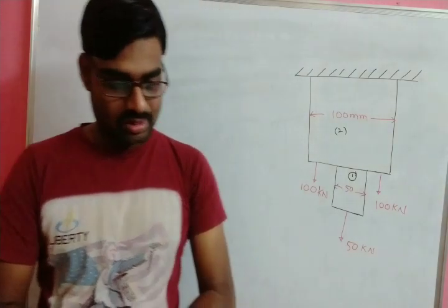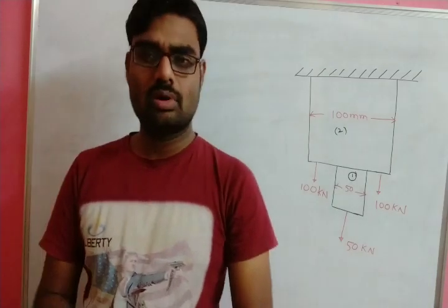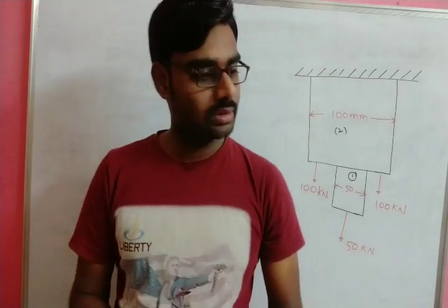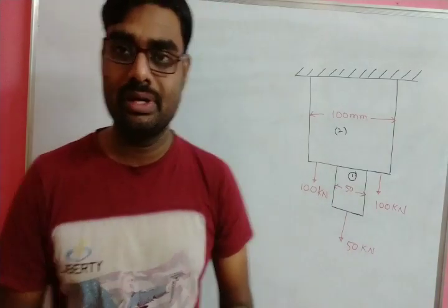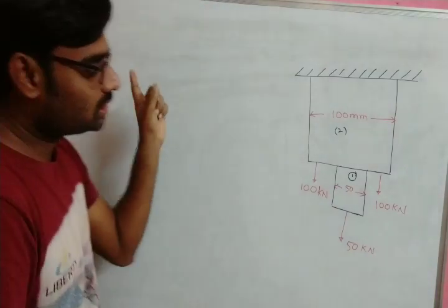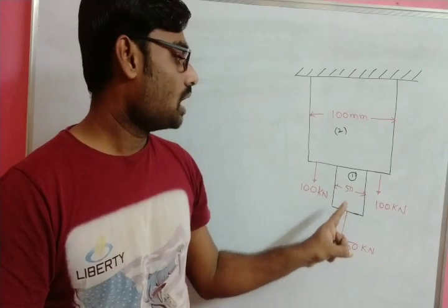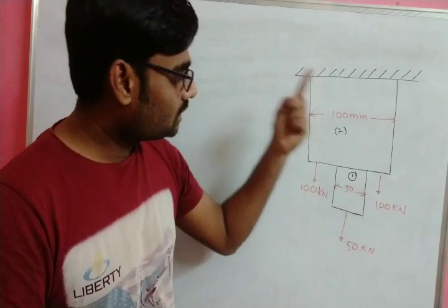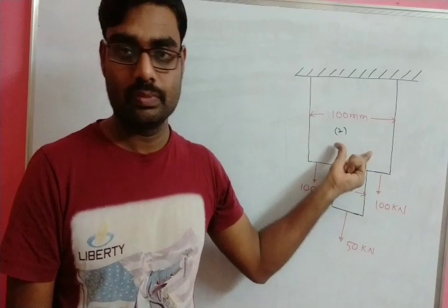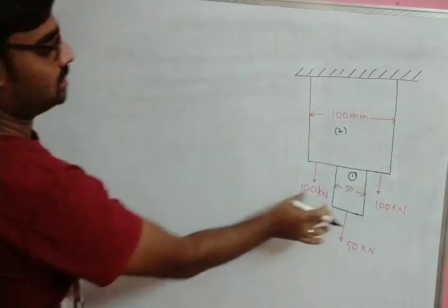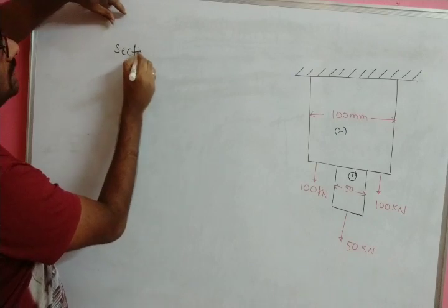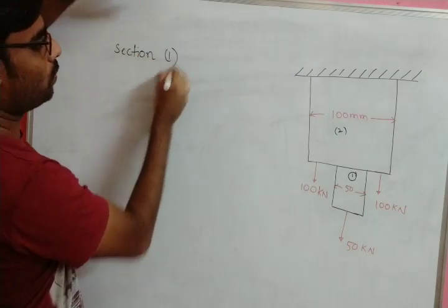So how to find out the stresses? We already know the formula: stress equals internal resistance force per unit area. Apply that stress formula to bar 1, and after that apply it to bar 2. So let us consider section 1.